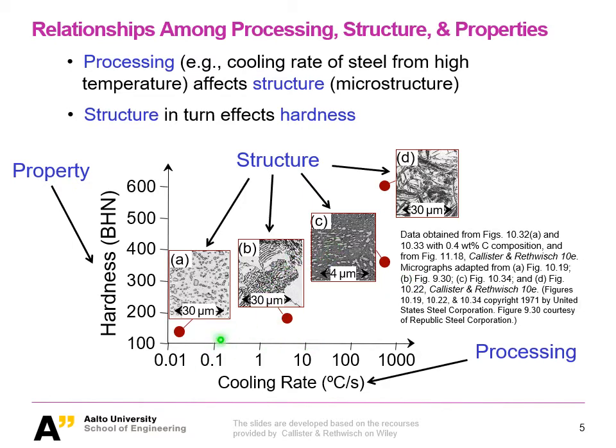They look similar, but why do they differ so much? They differ due to the size of the particle. If you look at the scale here, the particles in your tempered martensite, although they're both cementite, are much smaller. That is the key element to increase your strength and hardness.